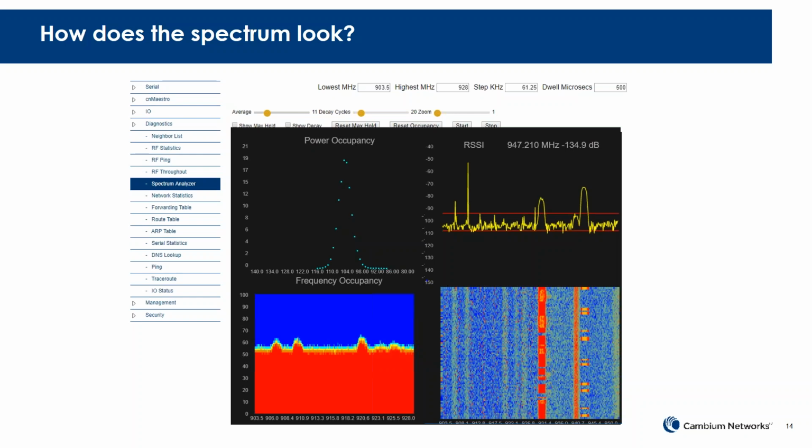If you look in the lower right, there's a waterfall curve. That waterfall curve is effectively representing what's above, but over about a 10 to 20 minute period of what's happened in the past, depending on the scan times. You can pick out the red bars showing when that signal was there all the time. And to the right of that orange bar, you'll see it going yellow and then blue back and forth. That is likely a polling host, and while the signal level is high, it's coming and going, so it's likely a polling system in a SCADA environment.